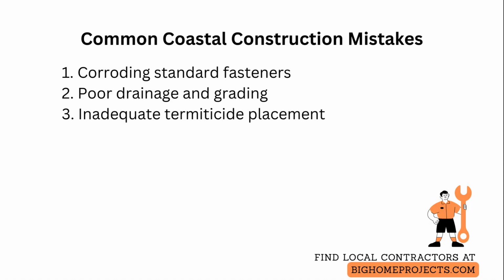A third frequent problem is relying solely on standard termiticide placements. Improve protection by combining physical barriers, treated foundation elements labeled for coastal conditions, and routine inspections, especially after storms, to detect and treat breaches early.